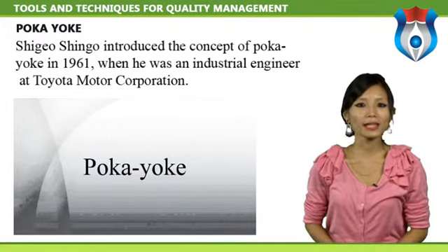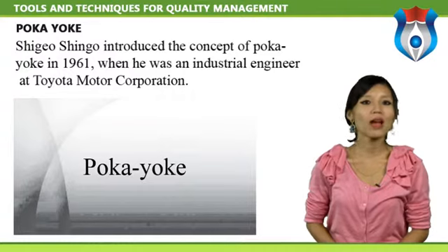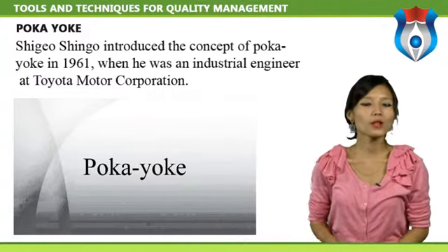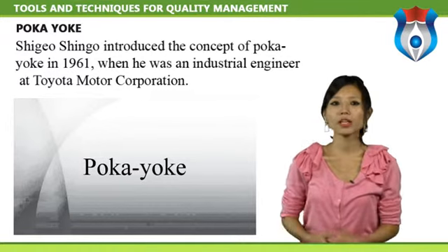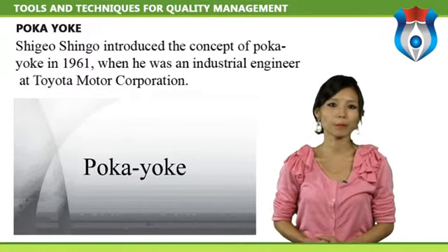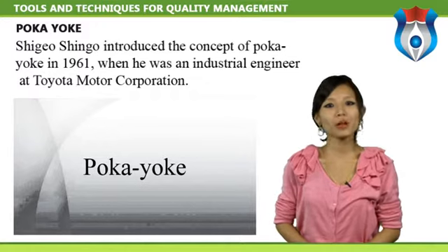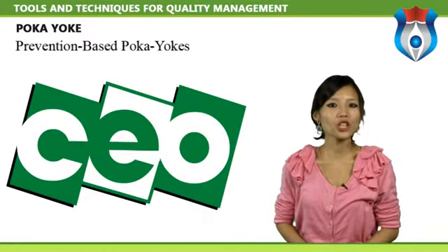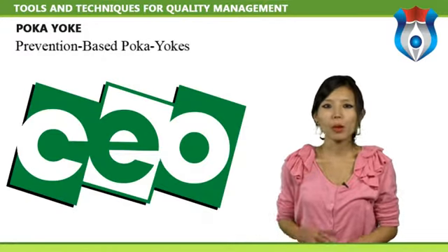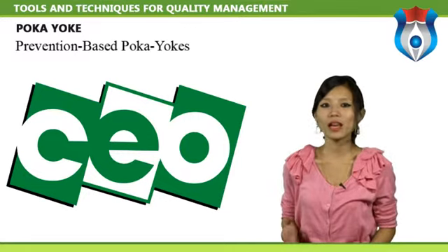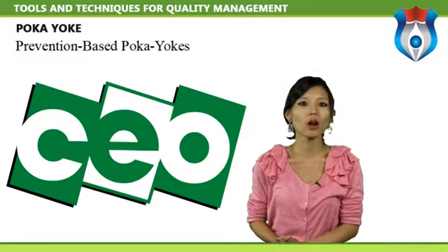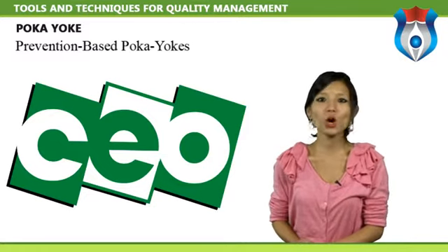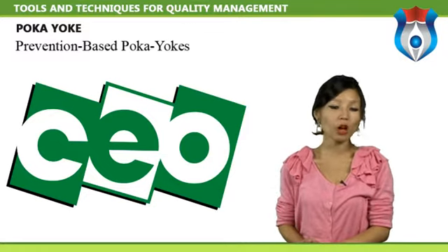The Center for Excellence in Operations (CEO) has developed a Poka-yoke framework to help its clients understand the various classification and application of mistake-proofing mechanisms. A brief overview of the framework is as follows. Prevention-based Poka-yokes. Prevention-based mechanisms sense an abnormality that is about to happen and then signal the occurrence or halt processing depending on the severity, frequency or downstream consequences.